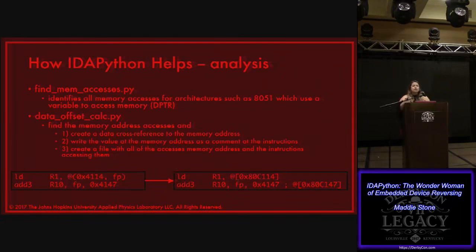And suddenly, for the Mitsubishi M32R, all of their special function registers and ports are memory mapped. So now I know that this value at port A is being read and written by these different functions. And oh look, it's not only one function that can set the value that is ultimately controlling this pump system. This one over here is the error case. And maybe I wouldn't have found that before if I wasn't able to say, this is everyone that's interacting with that pin. That really helps with saving time.